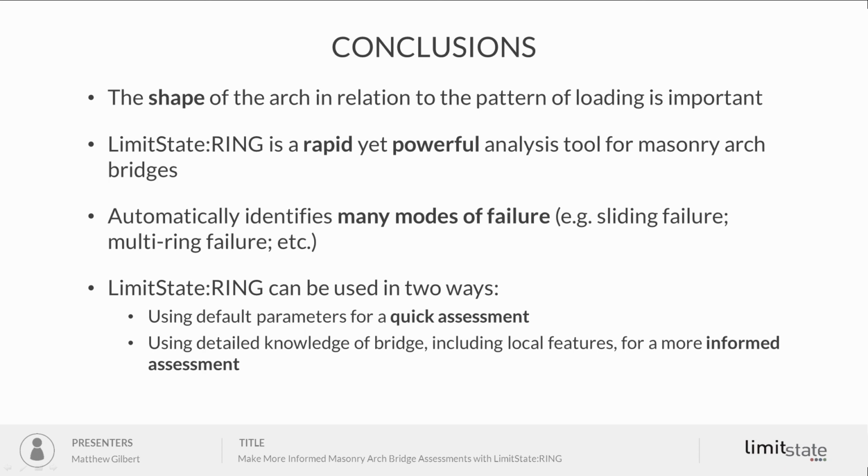It's just to identify here that when you're doing a site investigation, when you're looking at geometrical measurements, do take the time to measure the arch profile sensibly, and also consider what pattern of loading your structure is likely to be subjected to.